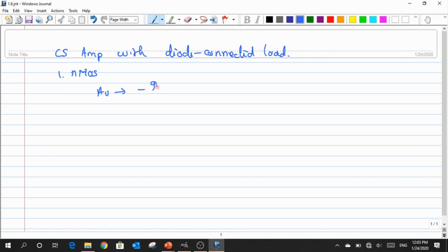So in the last class, we had discussed about this. Now in this case, first we started using an NMOS transistor. So NMOS transistor was being used, and we found that the gain was expressed as something like minus GM1 by GM2 with some eta factor, and this eta factor was a kind of problem for us just because it introduces a nonlinearity, right? So this was introducing some sort of nonlinearity into the gain expression, and we just want to eliminate this issue.